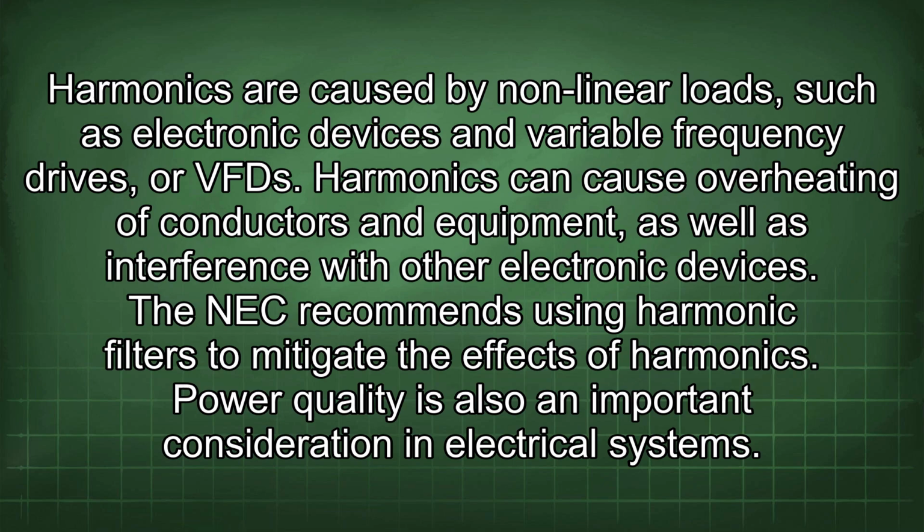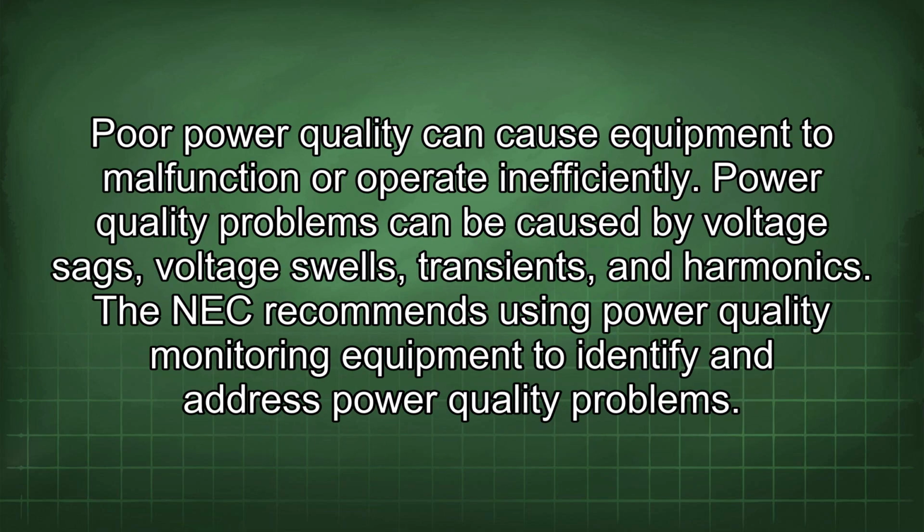Power quality is also an important consideration in electrical systems. Poor power quality can cause equipment to malfunction or operate inefficiently. Power quality problems can be caused by voltage sags, voltage swells, transients, and harmonics. The NEC recommends using power quality monitoring equipment to identify and address power quality problems.